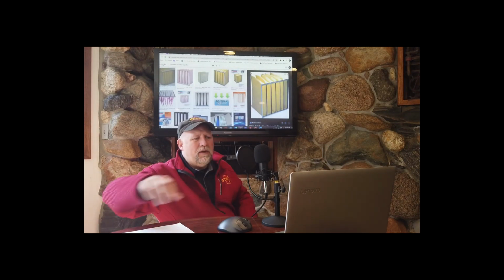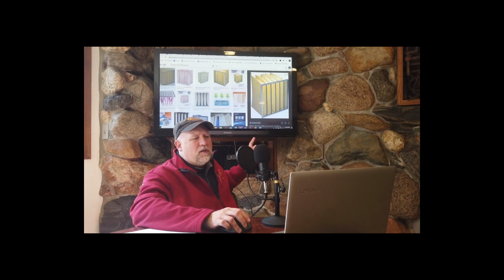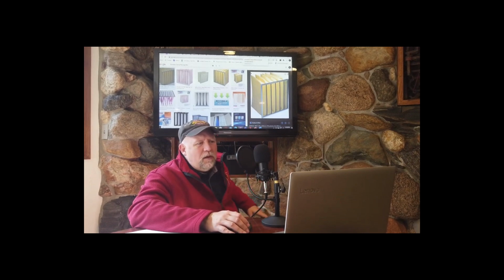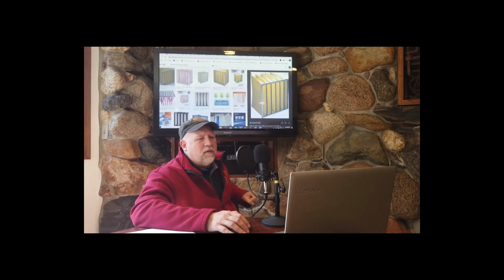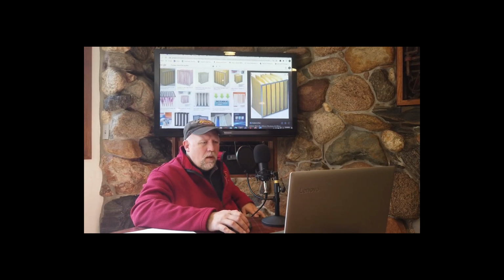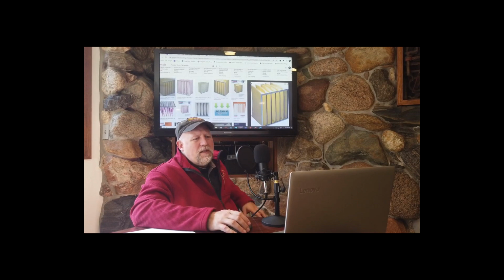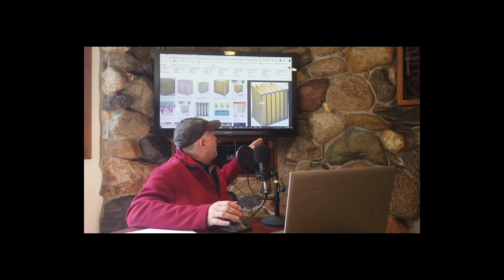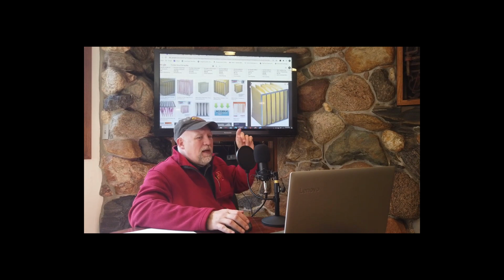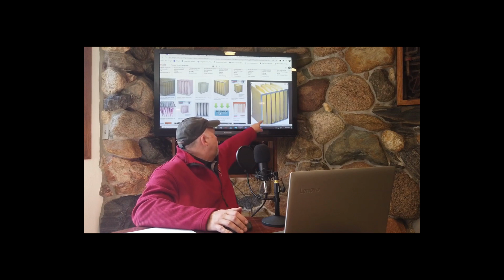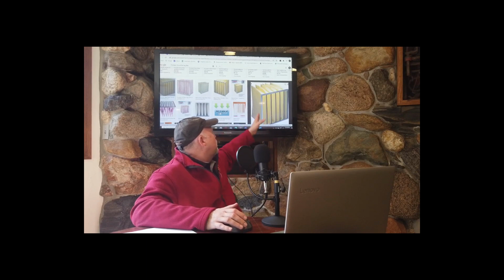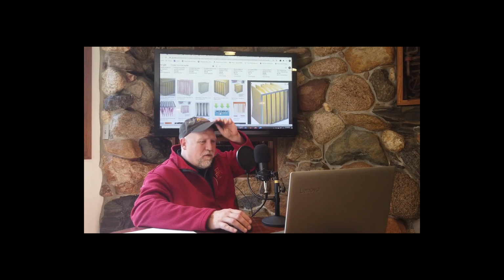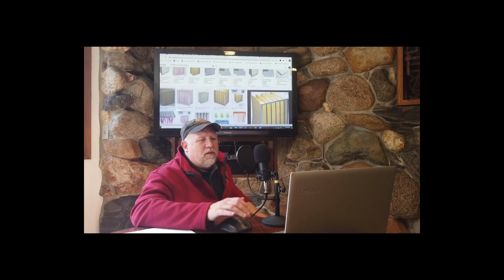All right, I've got a couple of different ones. First, before the Dominator, this is a bag filter, different type. This is just a different orientation. Notice this one. Instead of pleated media that's only an inch or two thick, this bag could be like 2 feet deep. The air comes in the pleats and goes through it, increasing the surface area for our filters.